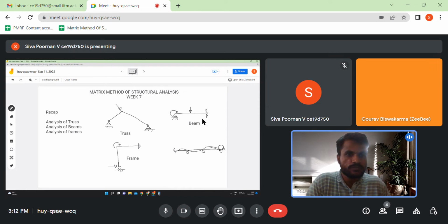You might be able to say it better because you have worked in firms. Software will definitely give answers, so we do a static check: whether all the load cases we have applied are being balanced by the reactions or not. That is also one check. You should be able to draw a free body and say that okay, the forces are all matching, they are in equilibrium.